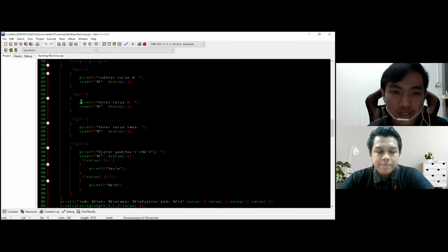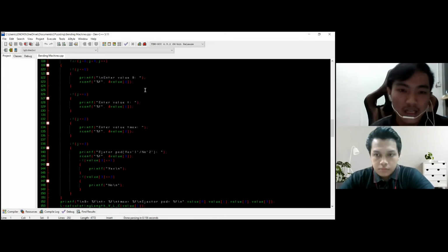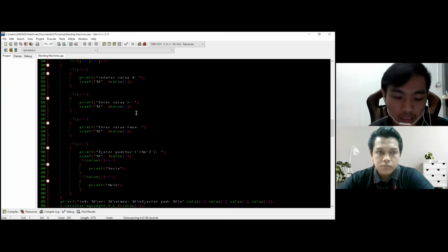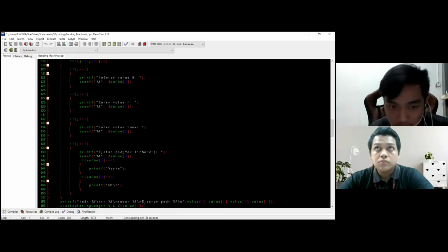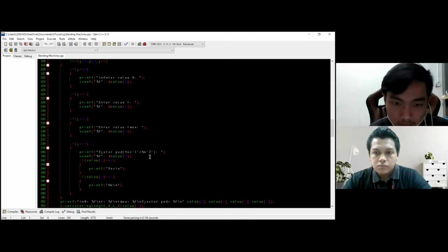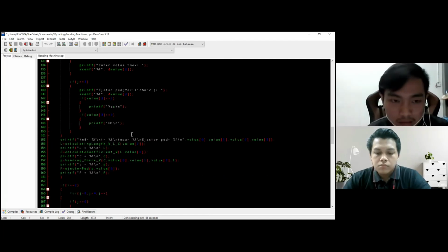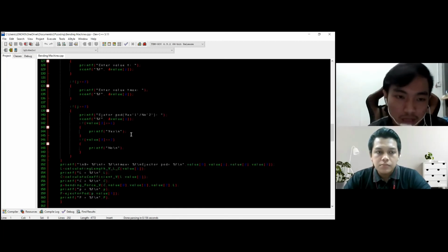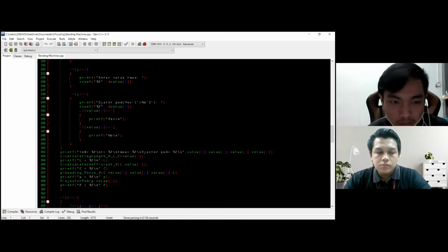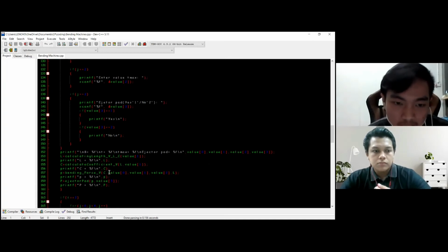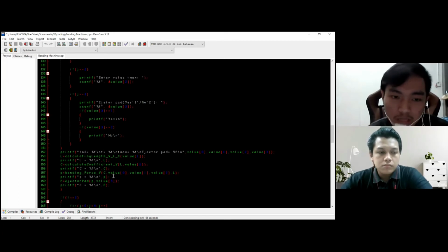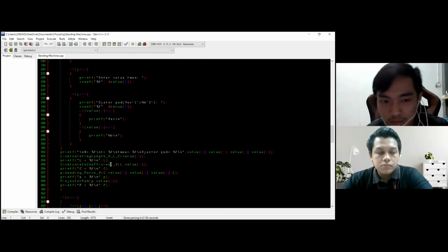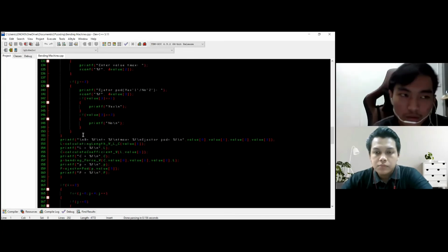The first value is B, which is bending length, the second value is T, which is thickness, the third one is T max, which is tensile strength, and the next is the ejector pad, where we put yes or no. After the process has been chosen and the values have been entered, the next step shows and calculates the length, the coefficient, and the bending force without and with the ejector pad, using the functions that were created before the main function.